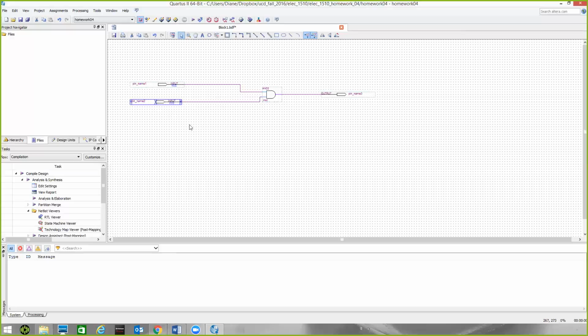Right. Now, we need to give these pins some names. Our inputs are named A and B, our output is named F. There's a couple of ways we can do that. One way is I like to go up here and turn on the text tool. Now, if I double click on that, or I highlight that in blue, I can just type A here, and it just writes over the top. By default, it said pin name 1. Now if I hit the enter key, it just goes to my next input, highlights that. So if I just type B, hit the enter key, I'm done. So we'll just go through my inputs. If I have multiple outputs, I can select that. Once I highlight that, I'm going to type F and.